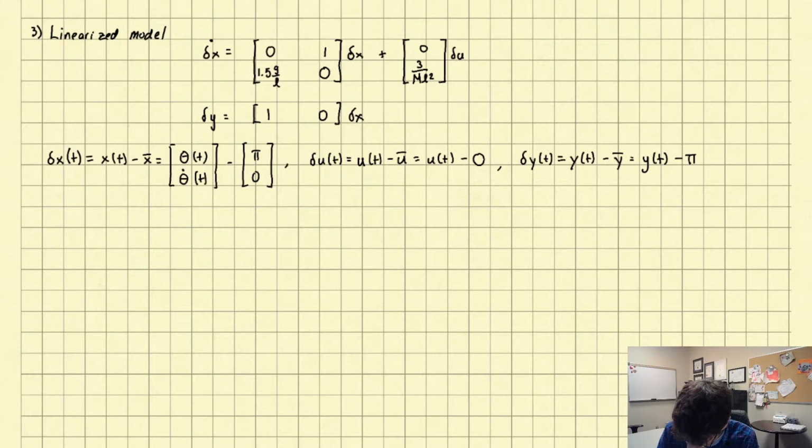So linearization. Now we have a way of going from a nonlinear model, which tends to arise through physics, and naturally systems will be nonlinear, and we have a systematic method to approximate them at an equilibrium configuration. Our objective, of course, is to then design controllers for the linearized model so that we can hopefully control the original nonlinear system. That's the objective here. We want to use our nice, simple linear tools to control nonlinear systems.